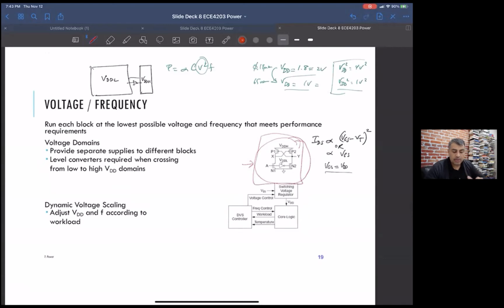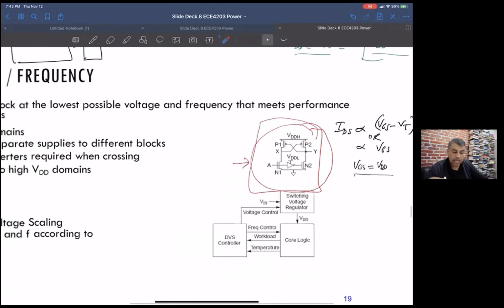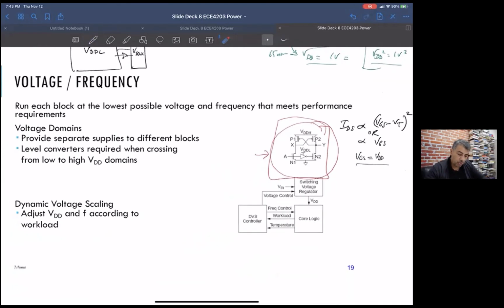So this basically has the PMOSFETs in a positive feedback loop. When the VDD low happens, it'll flip this positive feedback loop of PMOSFETs, and they'll drive the output all the way to VDD high. And you put those as a layer between your different voltage domain circuits. So that's very, very important.